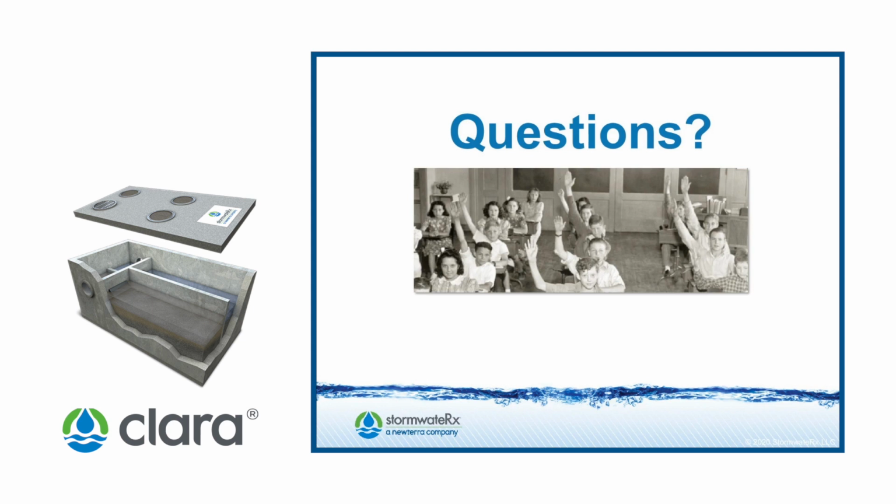We would certainly see, right, the media, insoluble zinc. The media is intended for a high hydraulic capacity, and for that reason, as you know, there are many different filtration medias available. Some that are sorptive and some that are inert. In this case, because we're expecting a high level of solids loading, sorptive media doesn't really lend itself well for that.